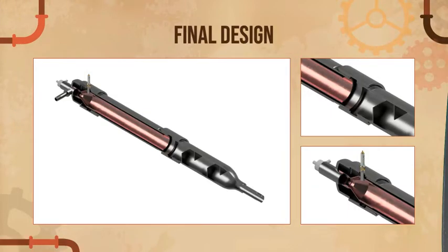And this is our final design. We chose elements from the third alternative with a simple heat exchanger. And for the mixing chamber, after several discussions with our client, we decided on baffles to provide the mixing of the two fluids. Water injection occurs via direct injection into the annulus between the shell and the tube, where the stream hits the curvature at a tangent and cycles around the heat exchanger.